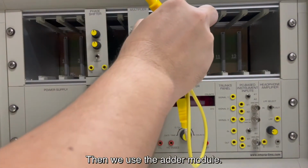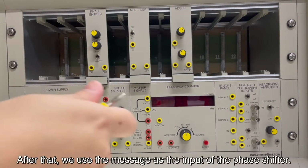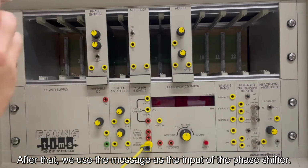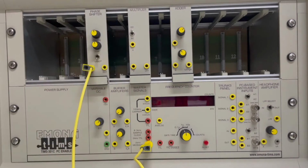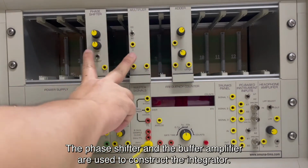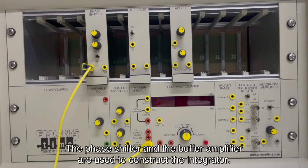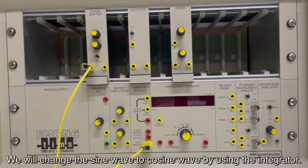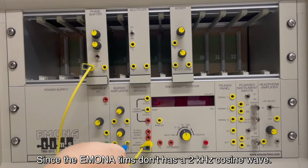Then, we use the adder module. After that, we use the message at the input of the phase shifter. Phase shifter and the buffer amplifier are used to construct the integrator. We will change the sine wave to cosine wave by using the integrator, since the simulator doesn't have a 2 kHz cosine wave.